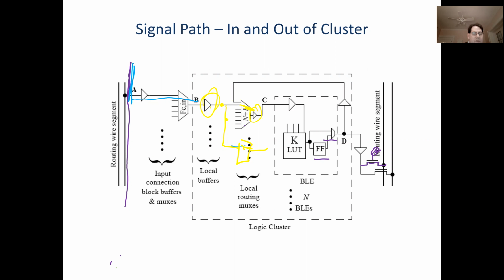So sending this signal through multiple multiplexers by turning on multiple pass transistors does slow it down a little bit, but not much, because most of the capacitance is actually the wiring. And we have a powerful buffer before and a buffer right after the mux to make sure we don't add more capacitance to this pass transistor inside the mux that it has to dissipate. So the effect's pretty small.